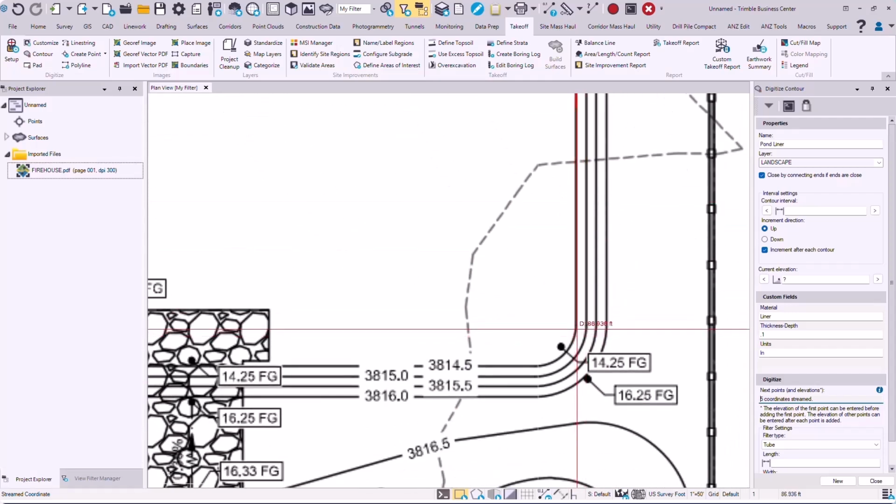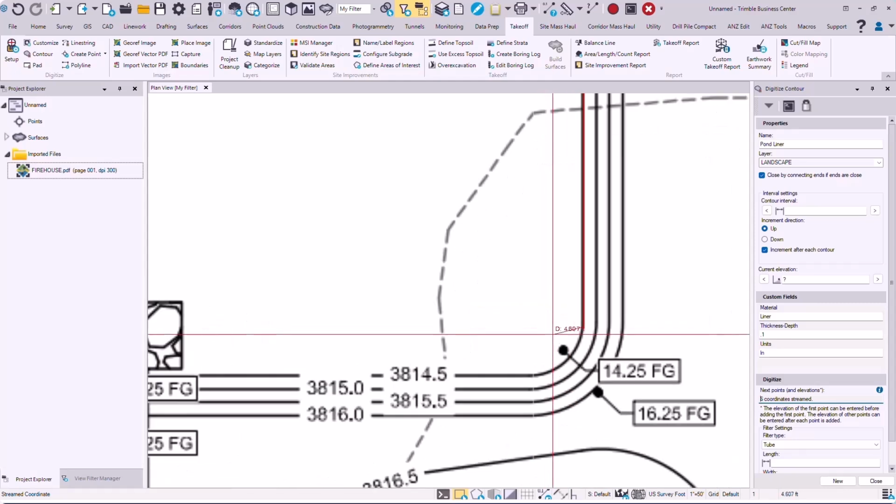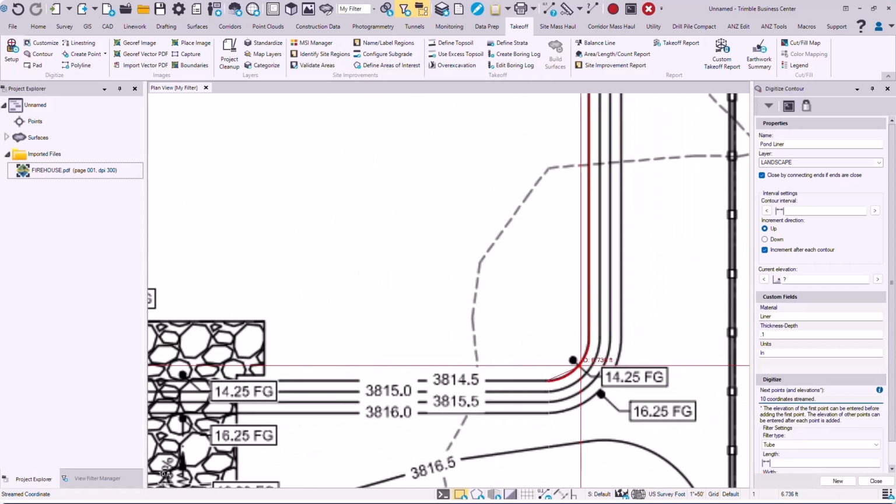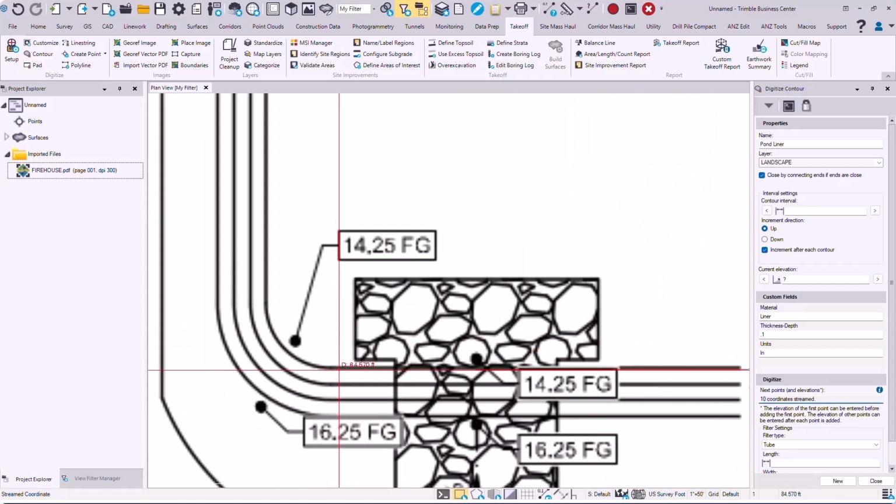Here I'll click a line here. That gives me that straight distance. I'll click the A one time and release for arc. I can click multiple points as long as I'm in the A mode. For arc, it puts that information in. We'll go back and hit the S for straight. So A for arc, S for straight.